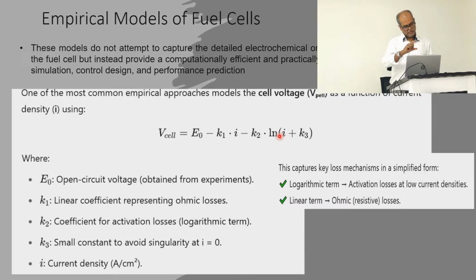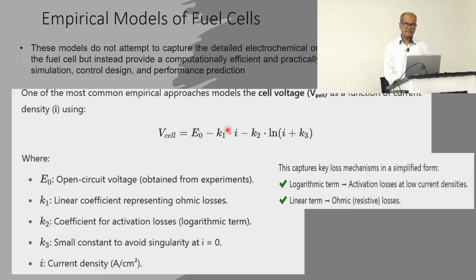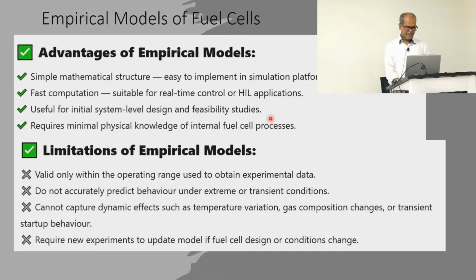And then you do have a characteristic curve. By playing with that, at the end you have to make sure that the characteristic curve matches the original characteristic curve of the fuel cell. So, that is how you are going to do the empirical model. Although it's quite simple, it's easy to implement in simulation like MATLAB Simulink. If you don't want to use the existing one, and if you want to develop it just like a simple equation, you can easily implement it in any software.